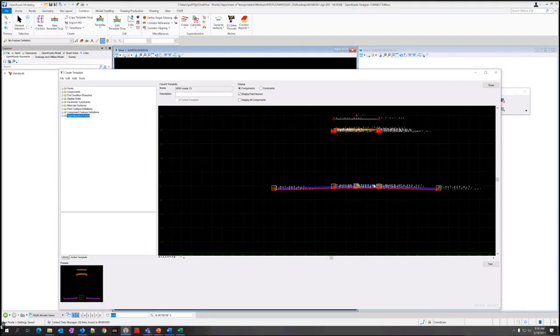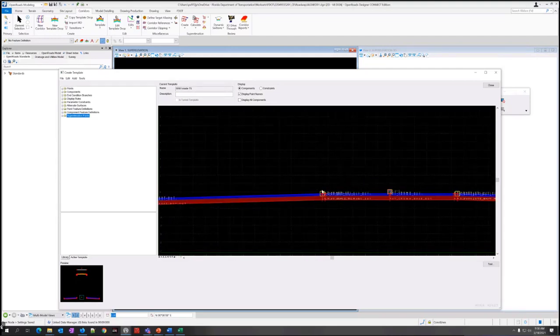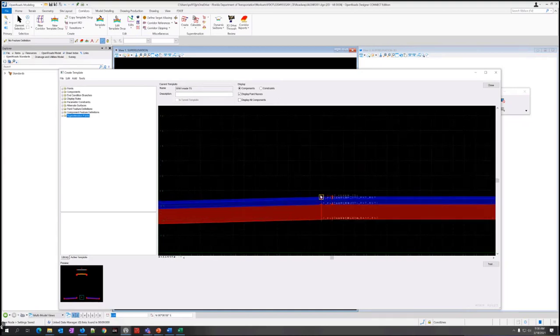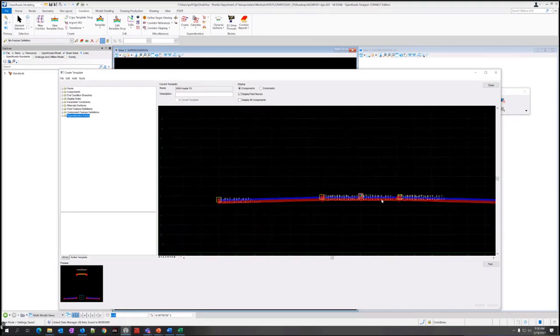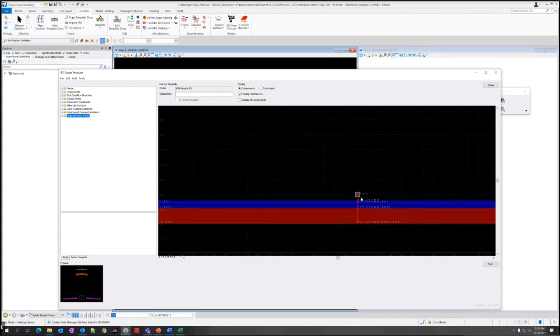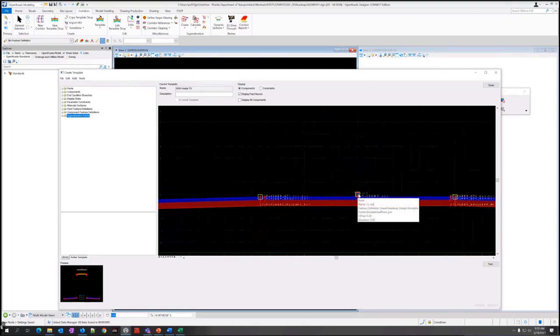One of the things I want to point out though, that's worth noting, because of the different options in F.Connect versus SS4 and SS10, there's a lot more super elevation options. To build it correctly, to be able to rotate about the center line for a divided roadway like this, we had to put a null point for the center line, essentially, and then constrain everything else off of it.